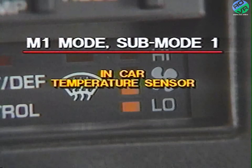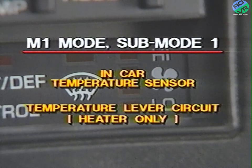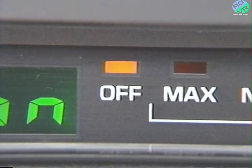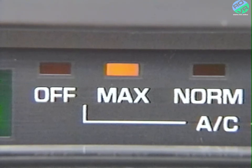Now, part of the M1 mode checks for faults in the in-car temperature circuit and the temperature lever circuit on heater-only systems, once again using the mode indicator lights to signal faults. As in the low mode, the lit off mode indicator signifies the absence of a fault in the circuits tested. But if, for example, the max mode indicator is lit, it indicates an open in the in-car temperature sensor circuit.